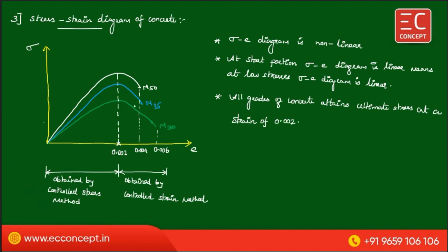All grades of concrete, see M30, M35, M50, and so on, attain the maximum stress at 0.002 strain, and all the grades fail at a strain between 0.004 and 0.006.